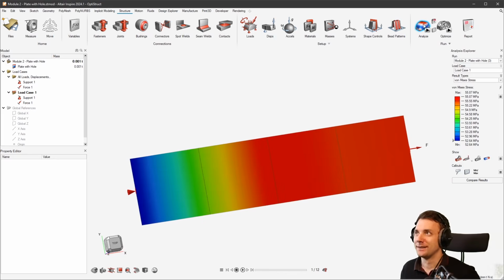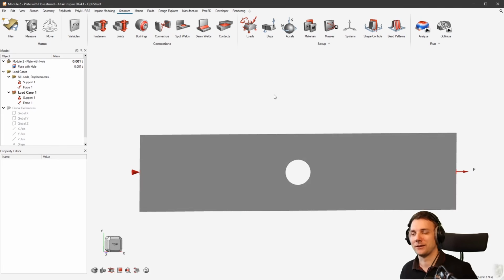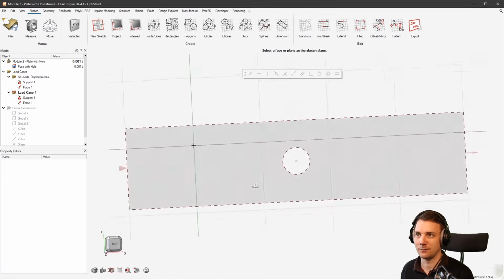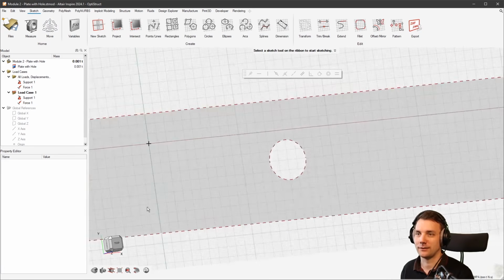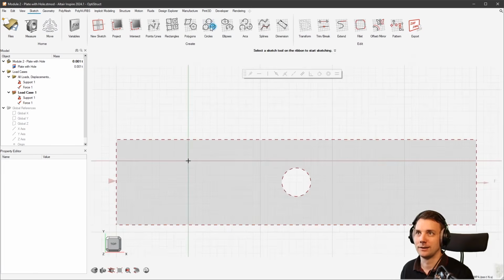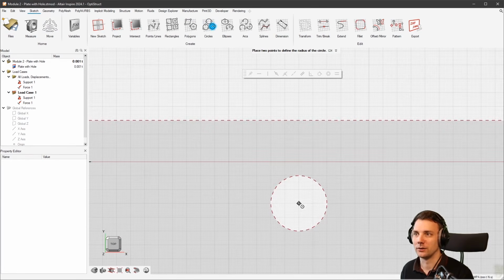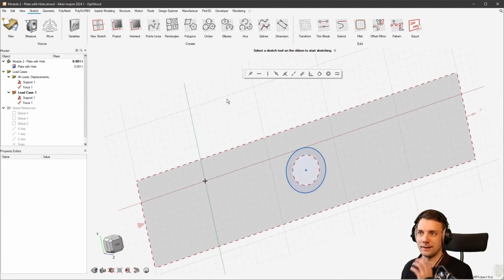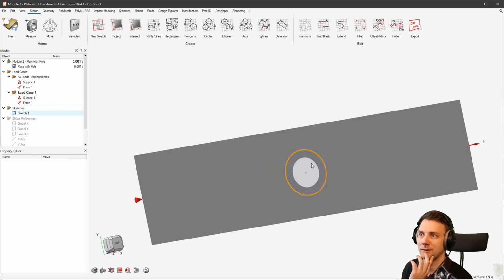and yeah, so just be careful about that. Good. Now I wanted to show you how to do a partition on this model, and this starts with creating a sketch on the part you want to partition. And then let's just add a circle around your hole here. So let's say this would be 40. Let's go with a buffer size of 20 millimeters. So roughly 60 millimeters.